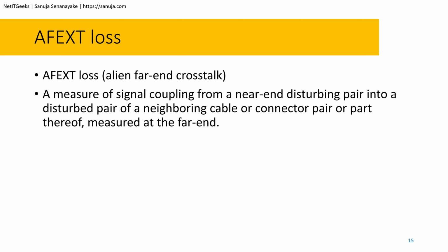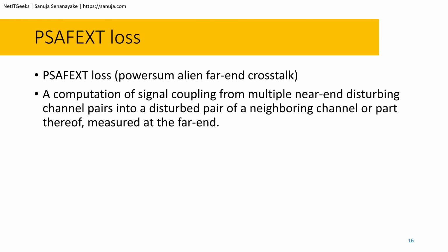FEXT loss, also known as the alien far end crosstalk. The definition is a measure of signal coupling from a near end disturbing pair into a disturbed pair of a neighboring cable or connector pair or part thereof, measured at the far end. Just at least remember the definition for your exams.